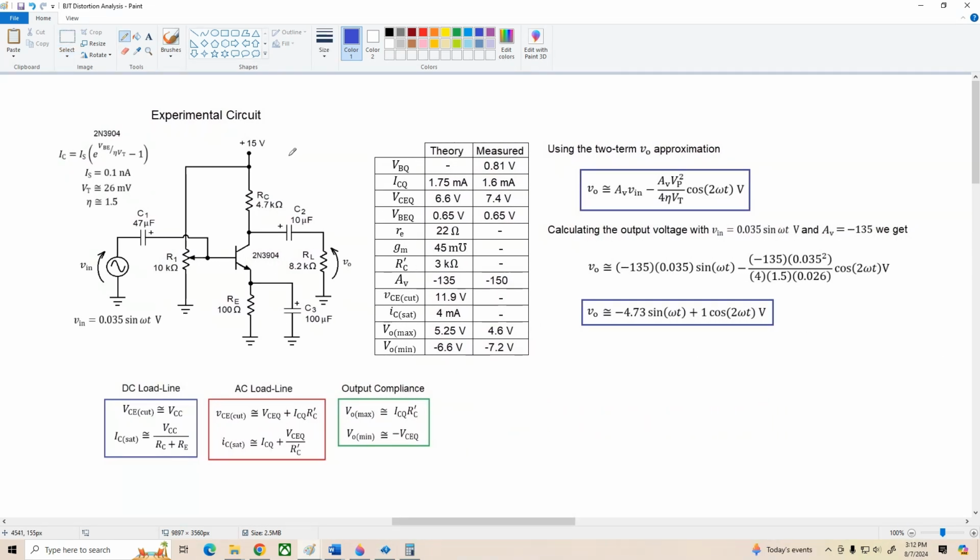All right, let's take a look at what we've got here. I used the transistor I talked about at the beginning of the video with these parameters set up as a voltage divider, biased, common emitter amp, full bypassing. I used a 10K pot to adjust my Q point, and the first thing I did when I built it was set VBEQ to 0.65 volts.